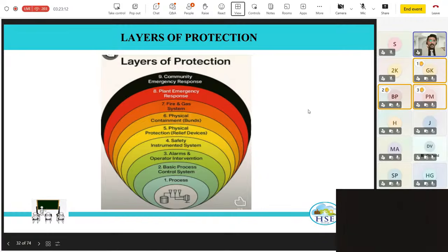These are referred to as ultimate safeguards because these are mechanical safeguards and they are not vulnerable to failures in your sensing element, your logic solvers, or any soft link. They are typically driven by the process parameters and they are mechanical devices, so they are bound to open.